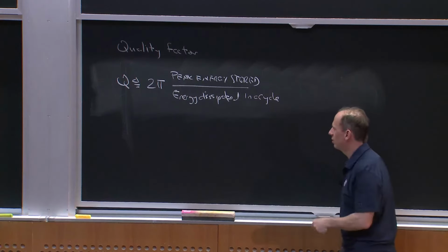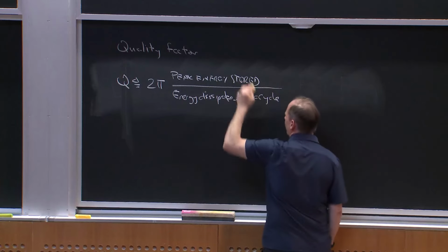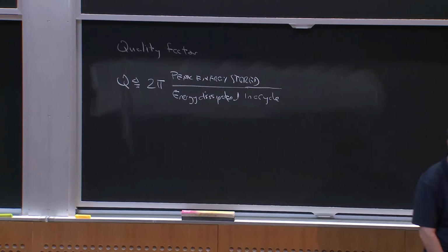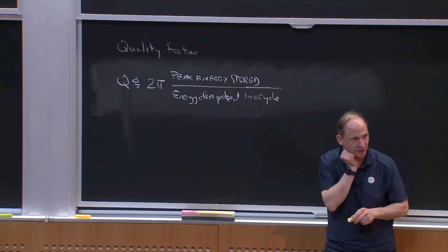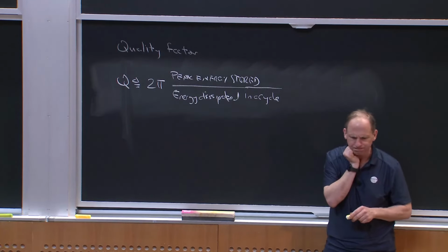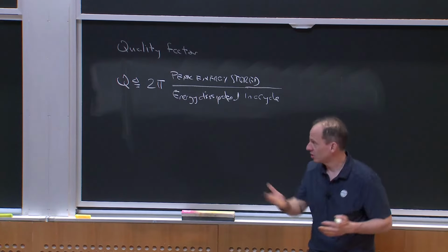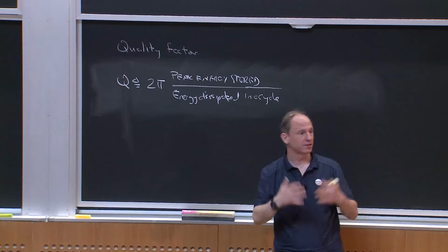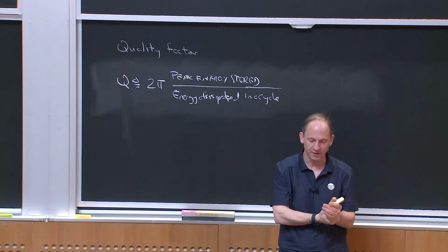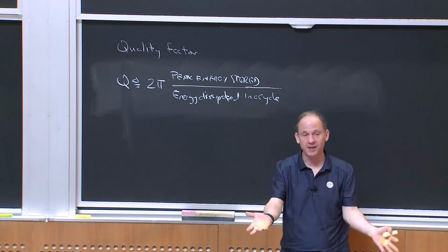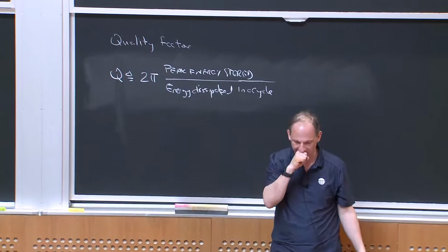And how the history of this sort of quality factor term came to be is actually in a handout that I think you should have been able to pick up, or it's also posted on Canvas. But this is the underlying, modern definition of quality factor. Let's just say, it doesn't only apply to second order networks like this, it applies to any network you're driving. And it also applies at any frequency you happen to be driving it.